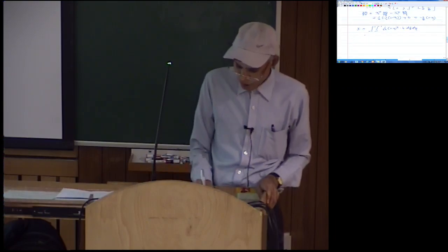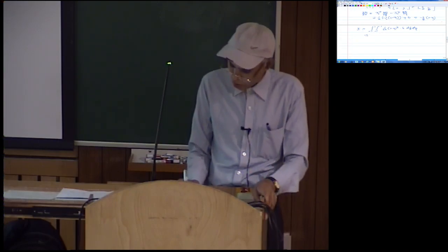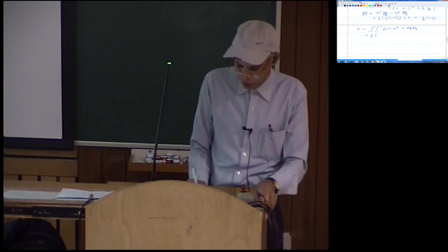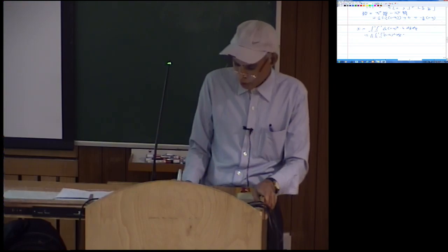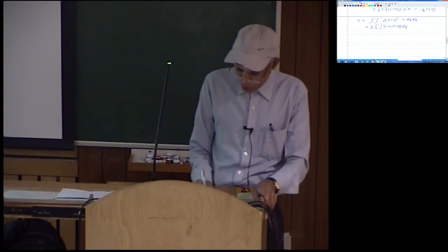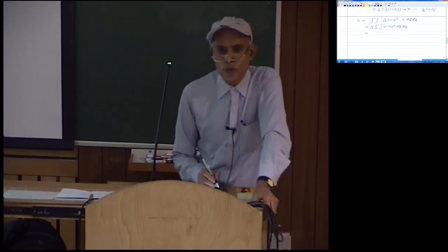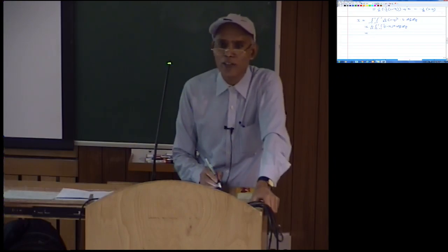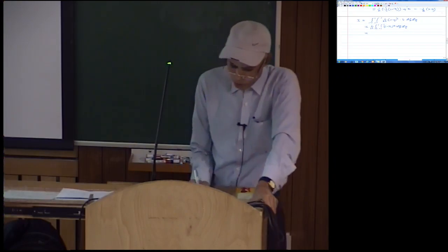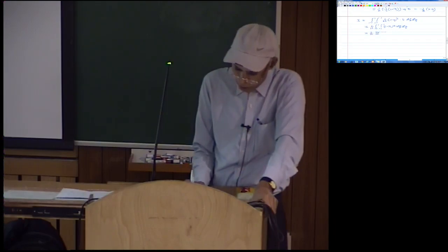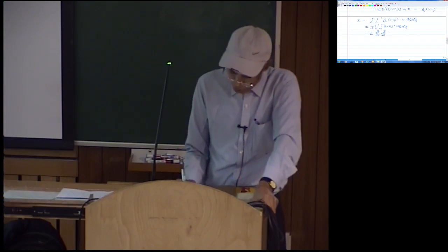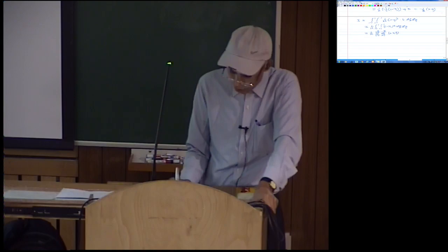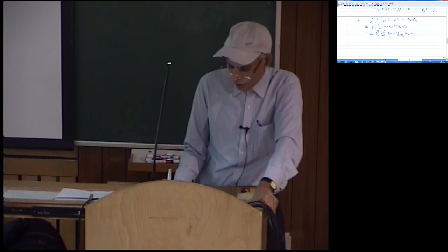So this is, and now we can of course take 4 by 64 as 1 by 16, integral from minus 1 to plus 1, minus 1 to plus 1, of 1 minus eta square d xi d eta. And then you now represent this. I had said to use 2 integration points along xi and 2 integration points along eta directions. So you represent it by a double summation, i equal to 1 to 2, j equal to 1 to 2, of the function 1 minus eta square evaluated at xi i, eta j, times wi and wj.